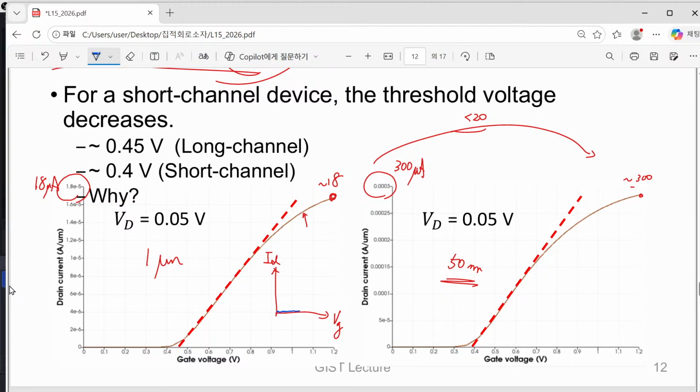Of course, below threshold voltage there is nothing, and when we turn on our transistor, now we have certain current conduction. But eventually when you increase your gate voltage too severely, then the effective electric field becomes too high. That introduces a reduction of your transistor mobility. So therefore now the typical curve just looks like this.